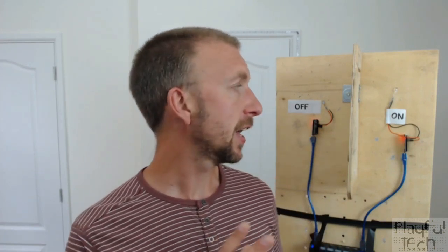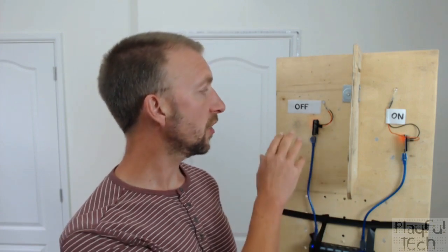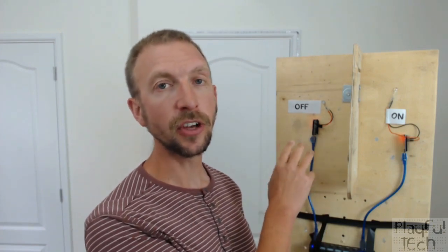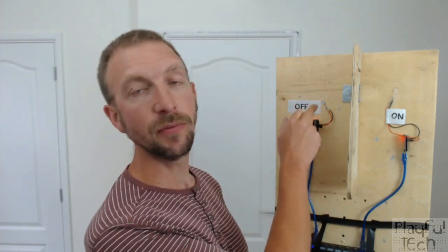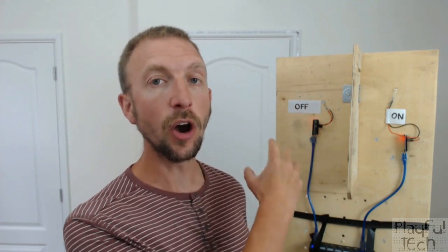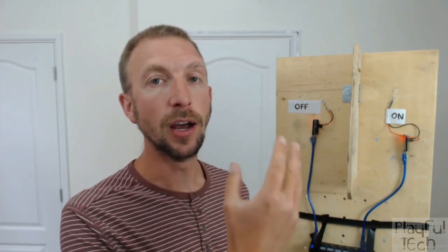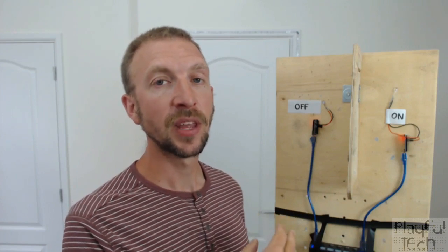So what I did was to take those codes that you see on the serial monitor output there and upload them to sketches running on two Arduinos on the board behind me. And these Arduinos have also got an infrared LED attached to digital pin 3. So the Arduino on the left here is going to be blinking this infrared LED using the off pattern of blinks and delays. And it's just going to be looping that over and over again.